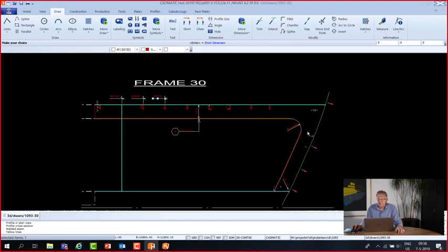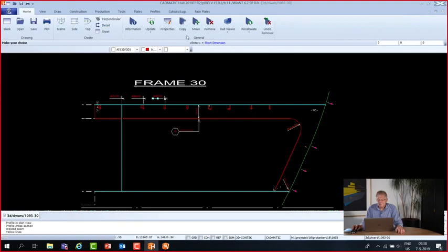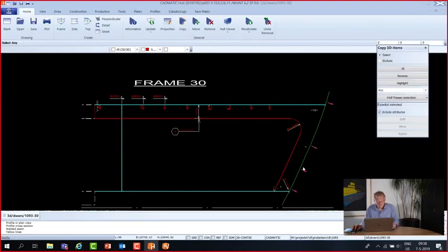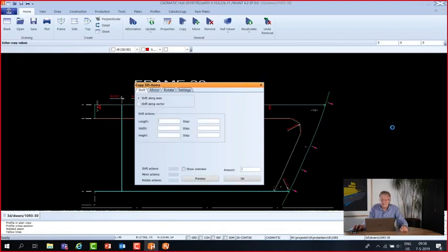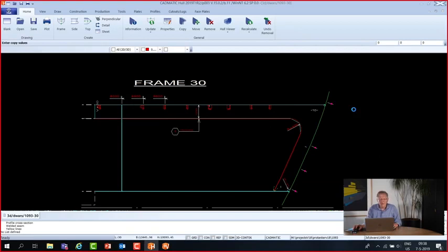this web frame on 33. So I will now use the copying command, copy the web, including the faceplate, and shift it 3 frames forward to frame 33. And here it goes.